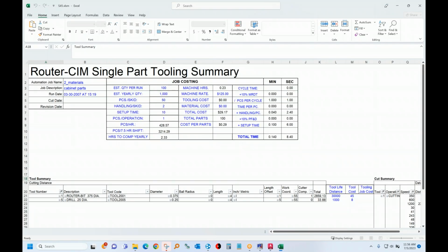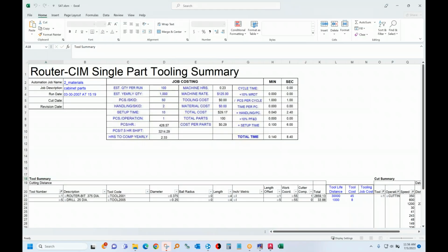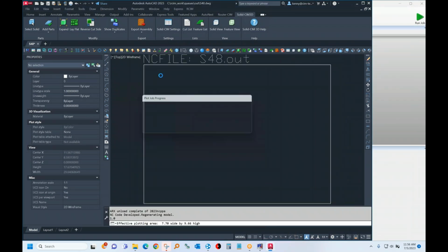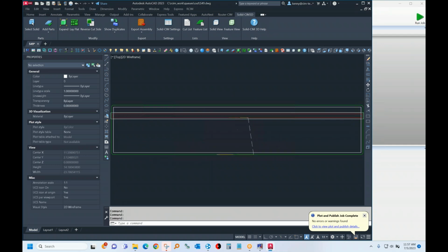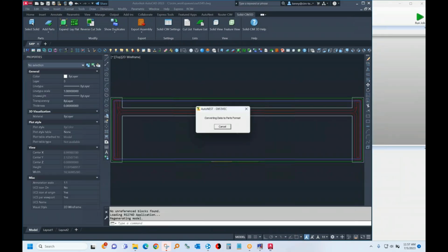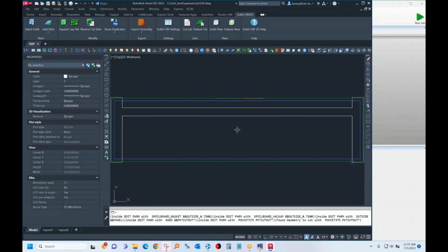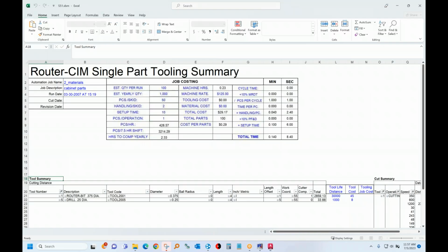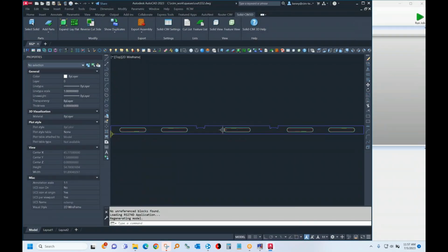I've got this set up to do advanced nesting with a stay down type of tool path, where the tool stays down and connects from part to part without lifting up. The single parts still have their outside, but when they're nested, it's going to be all one giant connected together tool path. That can cut your cycle time up to 20%. So it's a great way to save cycle time and get an extra 3 or 4 sheets of material cut in the course of a day. Instead of watching your router lift up and move over and lift up and move over, you can have automatic tool stay down and connect from part to part without lifting up.